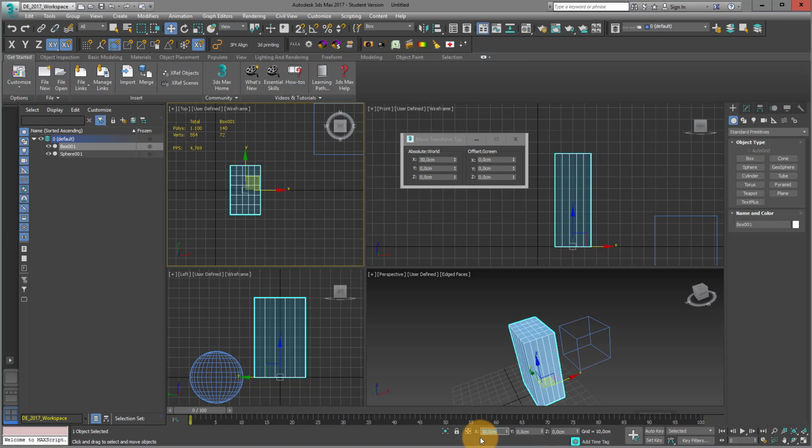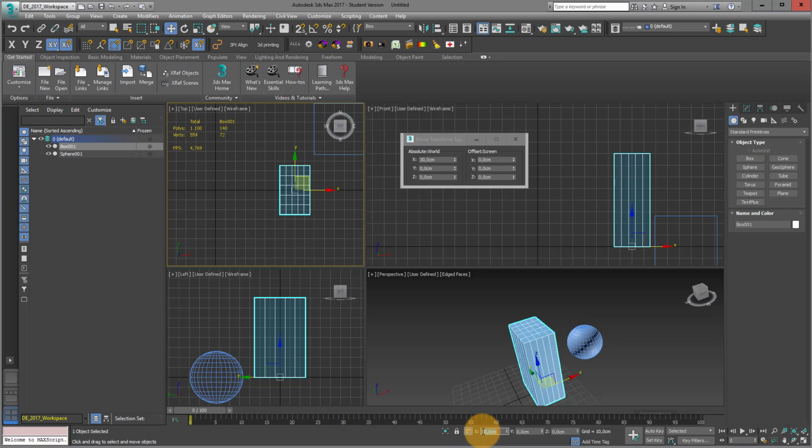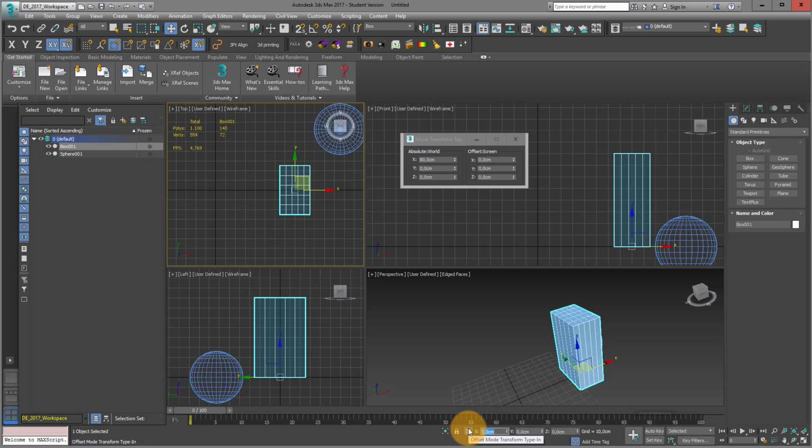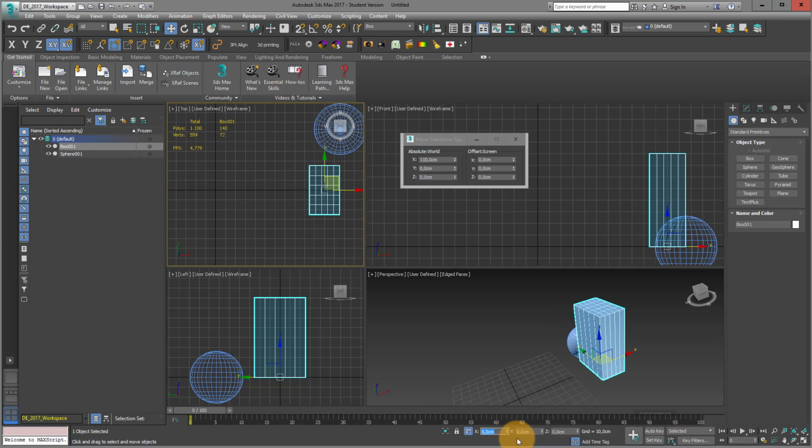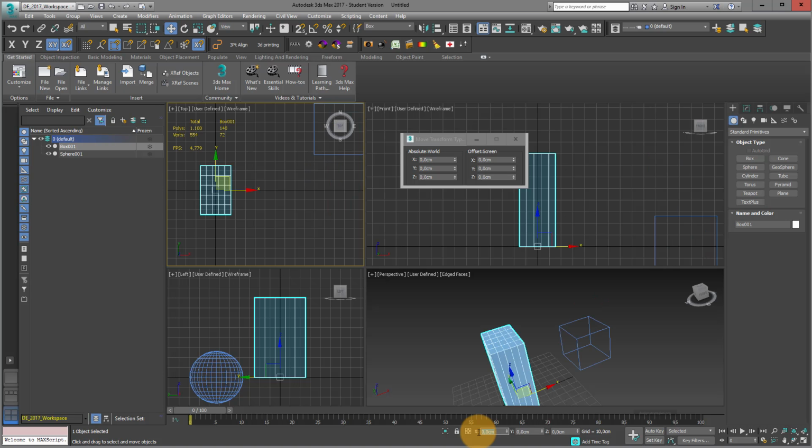And there's one field where you can change between absolute mode and relative mode. Now I'm again in this offset, in this relative mode. So here you can choose it like 30 centimeters, minus 30 centimeters from its own position. And if I just go back again into my absolute mode, and I just enter 0 here, then it's in the origin again. This is also a very good way of moving it.